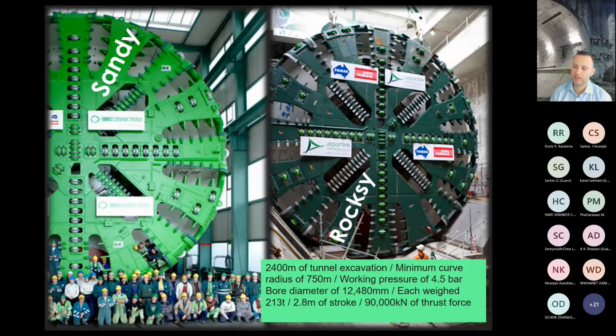Very specialized vacuums were needed for the ring build because they get very heavy. The segments were mostly fiber reinforced, but just the segments around the cross passages, because they need to take more load, we had full rebar in them.